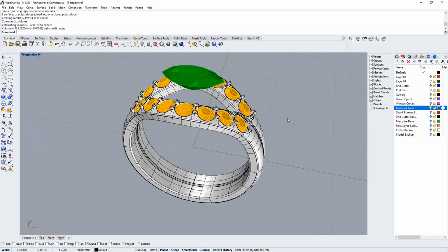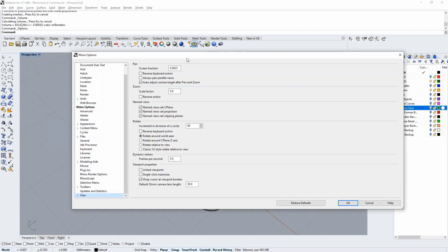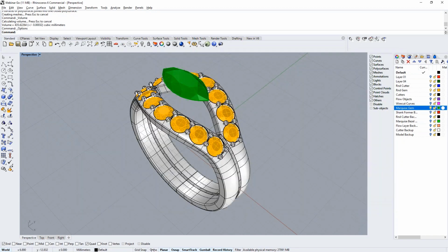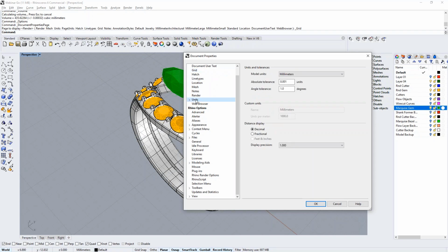So very similar there. John was wondering what your tolerance in this model is set to. I think my tolerances are just set to whatever the default in Rhino is. Let's take a look at that. Okay. Or wait a second, I don't need to go there, right? I can get to that through GridSnap, right? Sure, that would work. Yeah, just go up to units. So right under document, there you go, pick on that. There we go. Yep, so you have 0.001 set as your absolute tolerance there, and that's millimeters, so that's pretty darn tight. Yeah, that's tight.